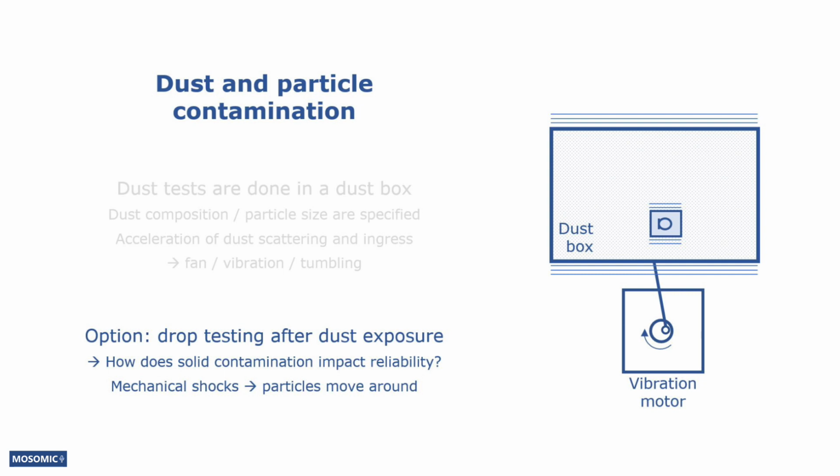of the MEMS sensor. This is based on the fact that mechanical shocks can cause particles inside the microphone to move around. In some cases, the mechanical shock may cause problems, and in some other cases it may fix a problem caused by a particle, at least temporarily.